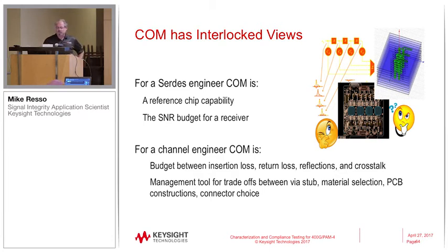It's also a very valuable tool if you're a channel engineer for design trade-offs between, what kind of via stubs do I want to avoid, what kind of exotic materials can I use, or what standard materials can I use, what design methodologies where it's microstrip, strip line, and then what type of connectors do I need. So it'll help you do a design of experiments, if you would like, during the prototyping phase.